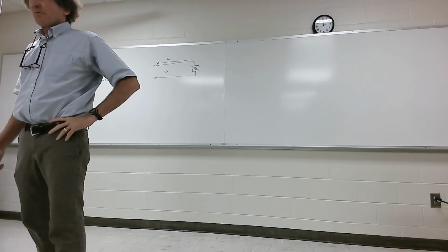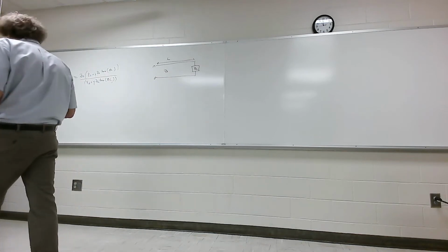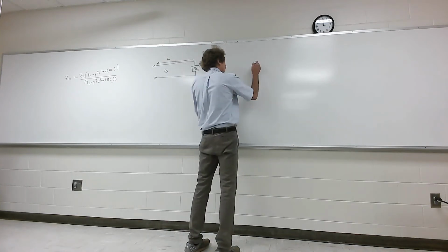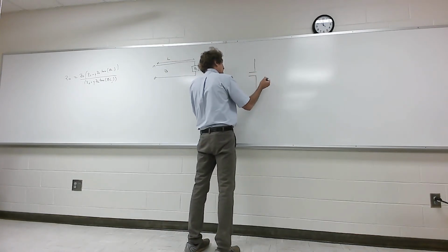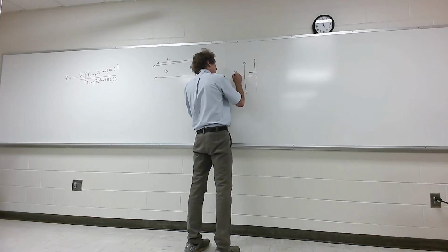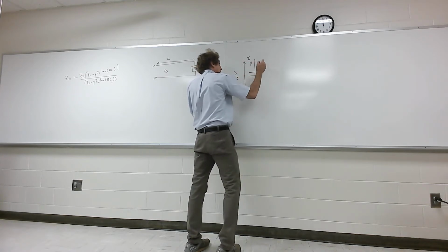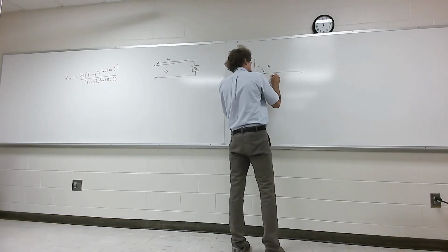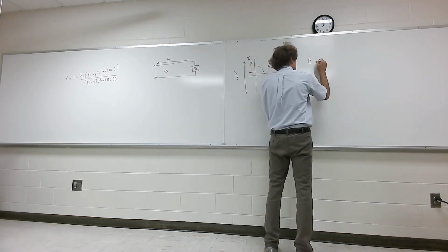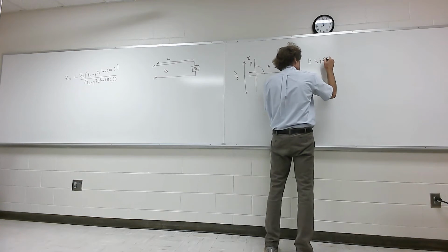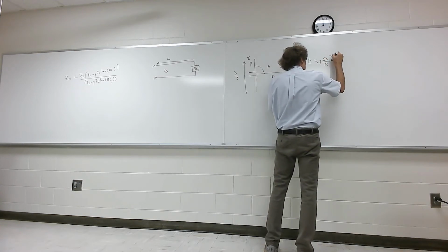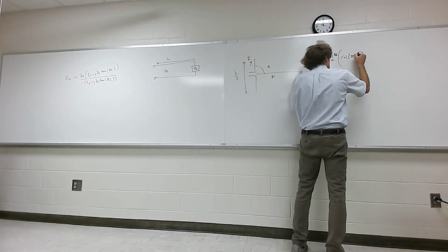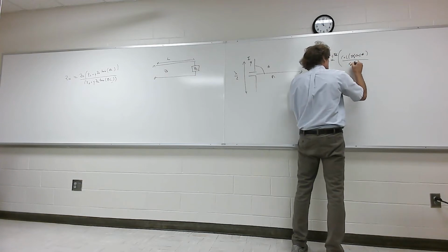For the half-wave dipole, if there's going to be a half-wave dipole, I'll give you the gain formula. And again, I'm trying to give you an idea of the things I'll provide for you. So for a half-wave dipole, I won't give you the short dipole, but if it's exactly a half-wave dipole, and you have a current I, then I know that the electric field at an angle theta and distance r, E itself for this one is equal to j, and then it's simply 60 I over r times e to the minus j beta r, and then it's going to be the cosine of pi over 2 times cosine of theta over the sine of theta.